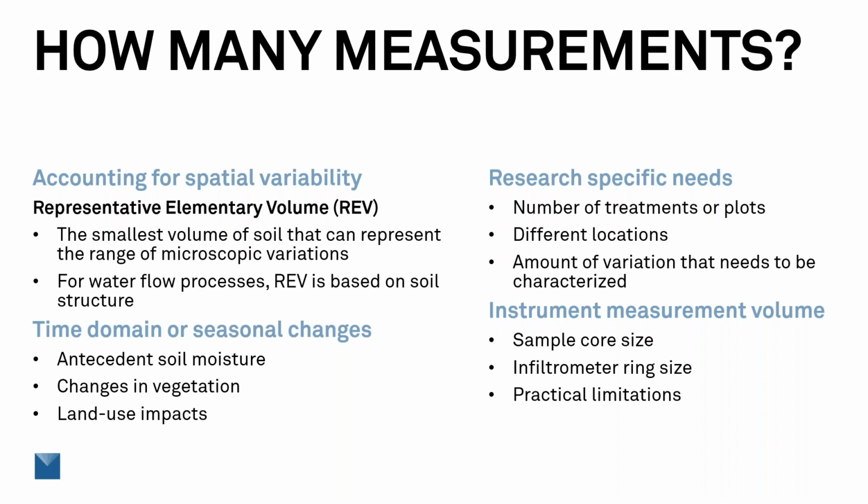So for water flow processes in soil, REV is primarily dominated or based on the soil structure. That's one of the biggest factors that's going to have an impact on how big of a volume you need to measure to properly quantify that variability.